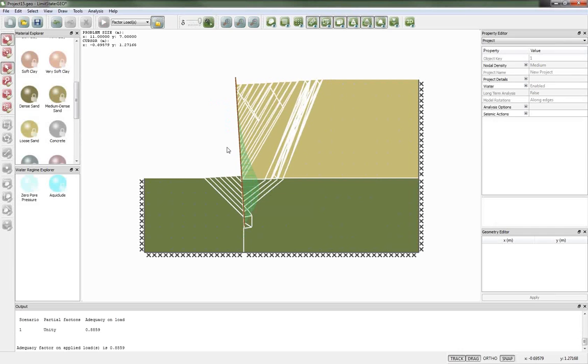Now, another point about ultimate limit state software: in this case, this is a bending moment distribution that would arise if we had a rigid wall. But rather than taking the bending moments from here and saying that's what we're going to design the wall for, it's actually better to get the software to find the collapse mechanism involving the wall, or identifying where a hinge might form. So we can set the bending strength of this wall, and the software can actually model bending of the wall. So here we've seen that we get bending moments of around about 48 at most.